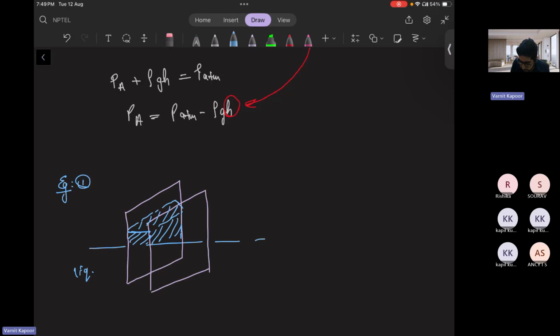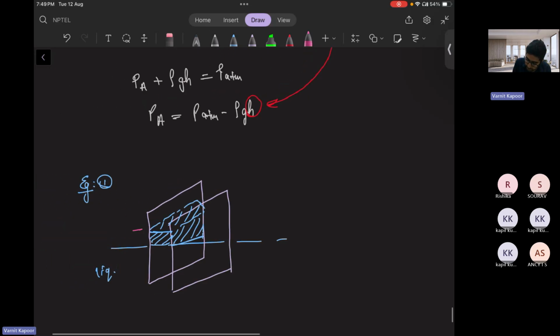Are you able to visualize? The liquid has risen up till here. So let us say the height is h again, till which it has risen. This is height h. Again, there is a meniscus at the interface. A meniscus will form, and again it will have sigma, vertical and horizontal components of that sigma. So vertical component sigma cos theta, sigma sin theta. Here also it will be sigma.